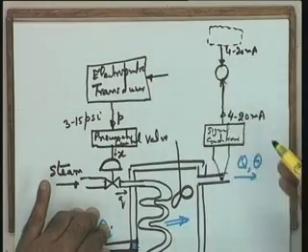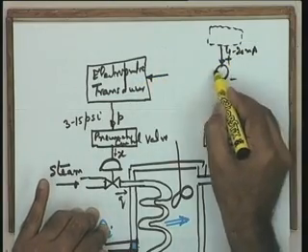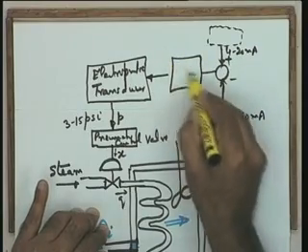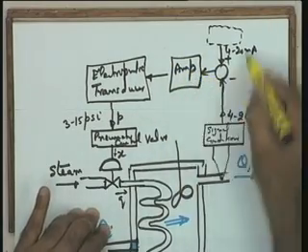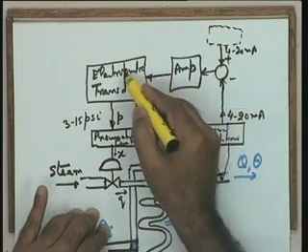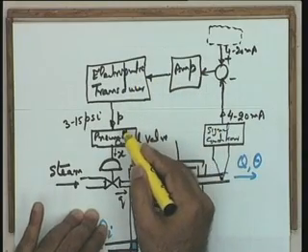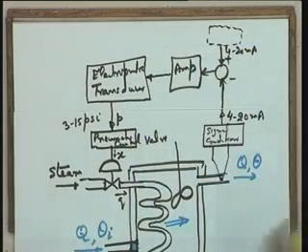This comparison over here is done in this error detector, plus minus, and let me say that I have an amplifier. I am taking all in terms of currents, suitable voltage conversions and comparisons are possible. So, this is an electrical signal to the electro-pneumatic transducer which is generating the appropriate pressure signal, and hence this becomes the total device which is very much in use in industry as far as process control applications are concerned.